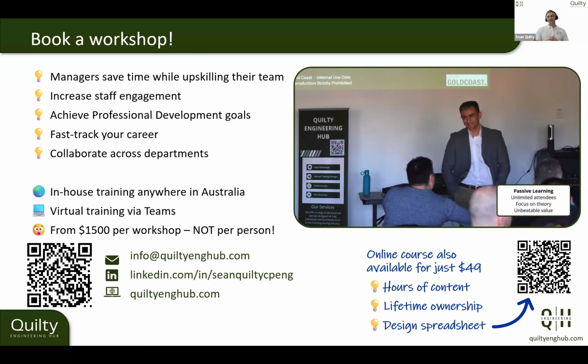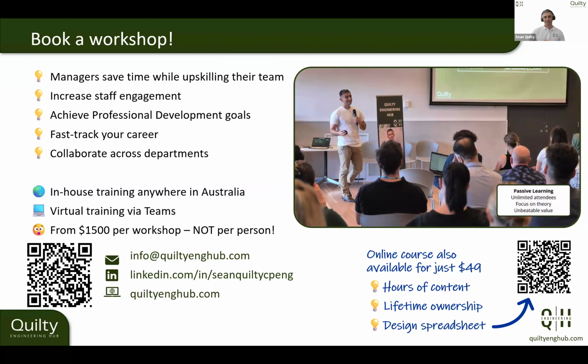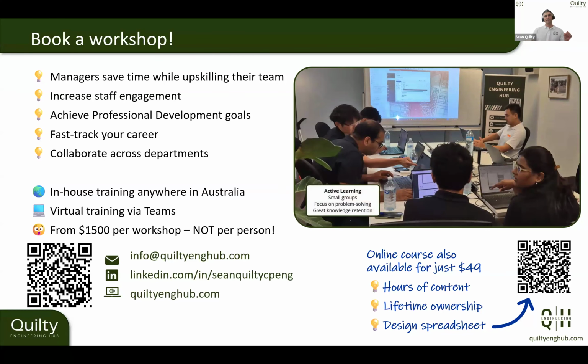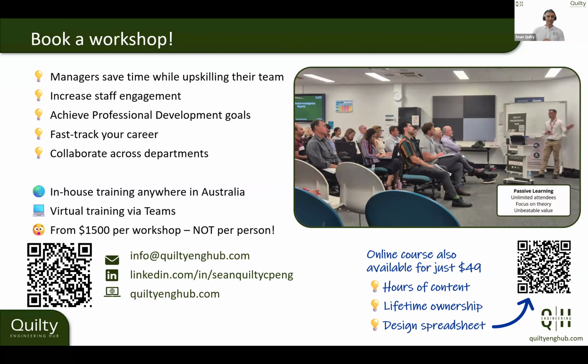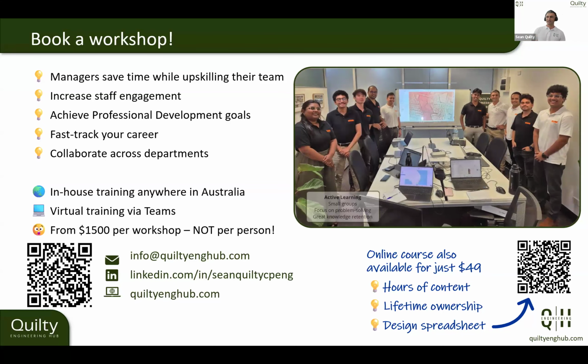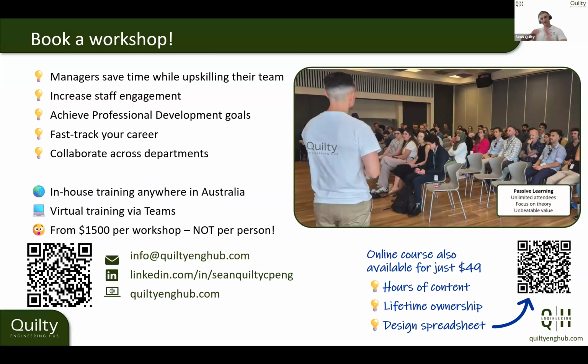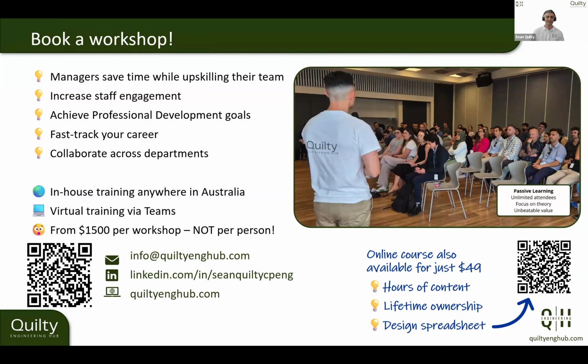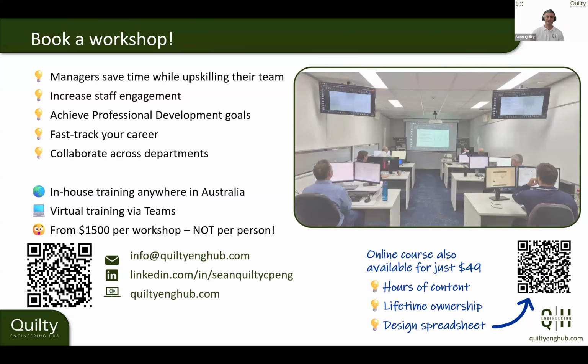The maximum depth. There may be some requirements where councils might put something in place, or some guidelines might put in place where you don't want a certain amount of depth. But the more common parameter that we use is the depth velocity product. That's where you take your depth and your velocity and multiply the two. Then there will be a threshold where we found that any more than that value becomes dangerous. As an example, a DV of 0.6 square meters per second. So it's like this flow area that's flowing every second. That's a pretty common one to use for safe channel design.